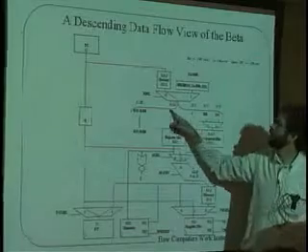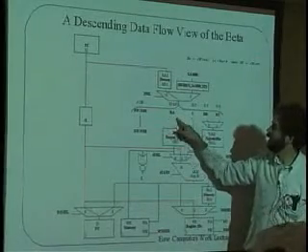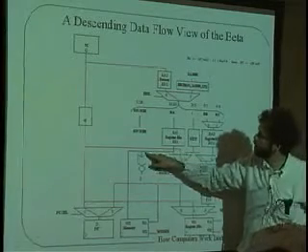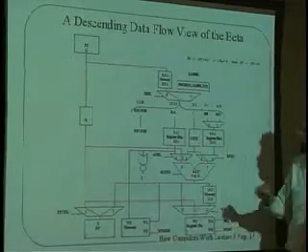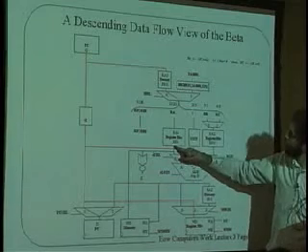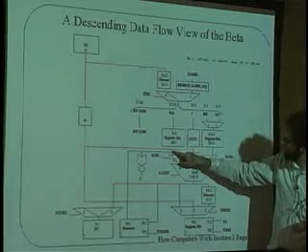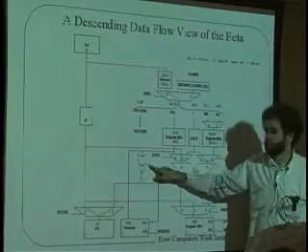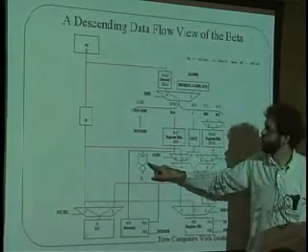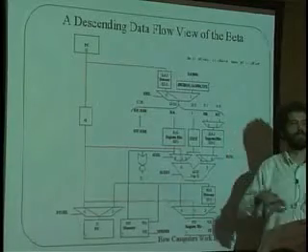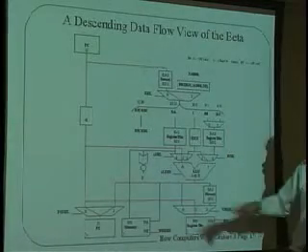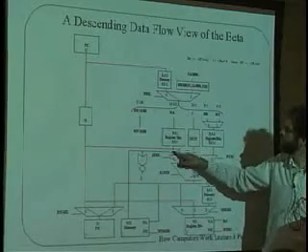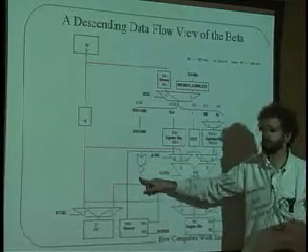The register that we choose to be register A comes out here and gets read here, and unfortunately I didn't make this read by last night, but the output of the contents of register A comes out here and goes into this gate here, which we're going to talk about in the next class, which is a gate to test whether or not the data there is 0. And that comes out as Z here. Is it 0? And so we're going to test the contents of register A like so.